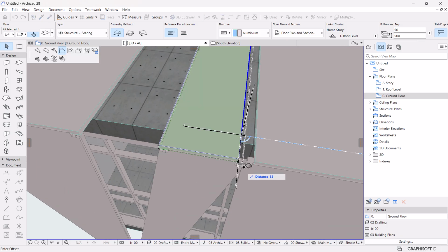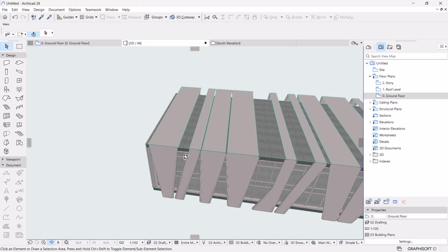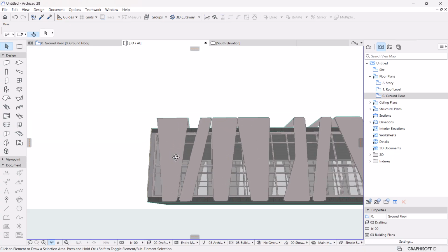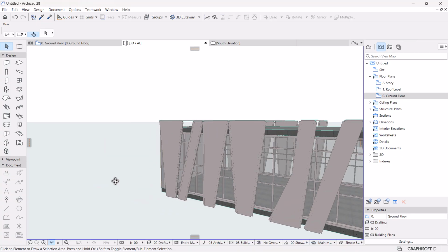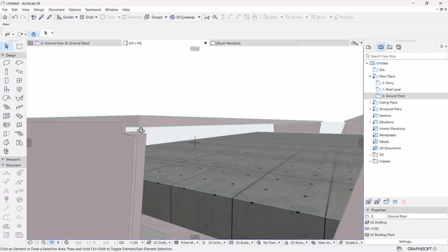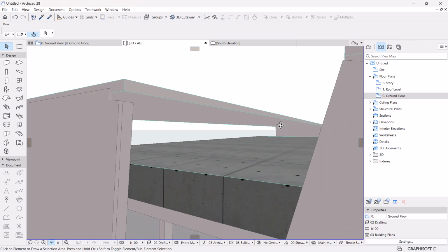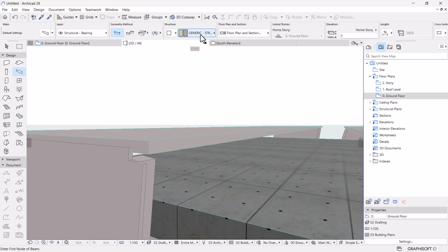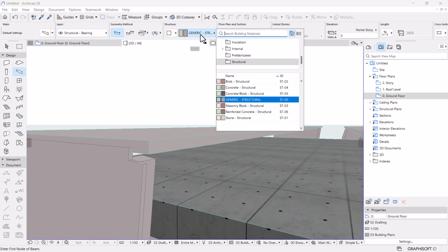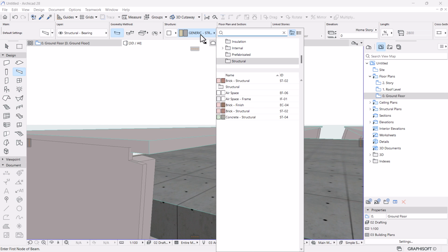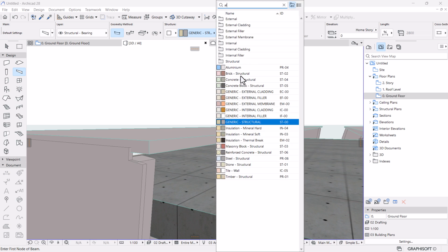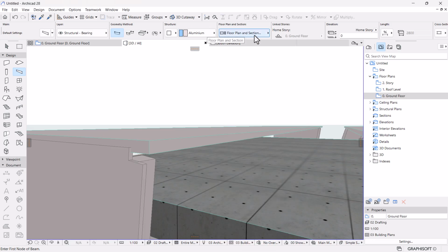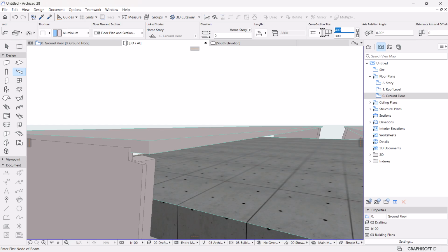like that, but this we could do at a later stage. For now I want us to focus on that. From here, because this frame needs to continue all the way to the underside of the slab, for example, you will have a beam of the same size. This will be for aluminum, and the height, I made it 100, then this was 80.